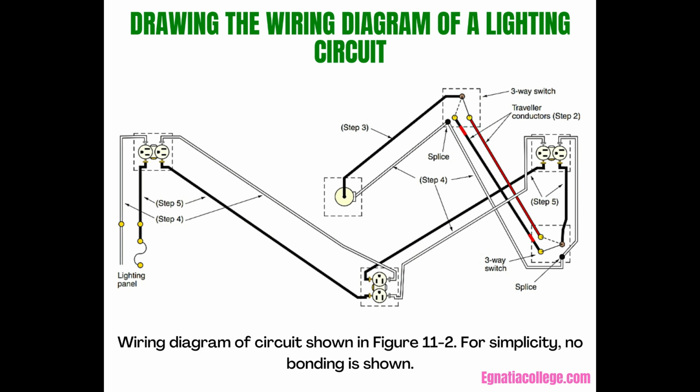This is the switch leg. 4. Draw a line from the neutral bus bar on the lighting panel to each current-consuming outlet. This line may pass through switch boxes, but must not be connected to any switches. This is the white grounded circuit conductor, often called the neutral or identified conductor. It is not truly a neutral conductor unless it is part of a multi-wire, 3-wire circuit. Note: An exception to step 4 may be made for double pole switches. For these switches, all conductors of the circuit are open simultaneously. They are rarely used in residential wiring.